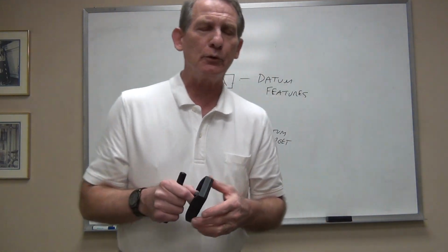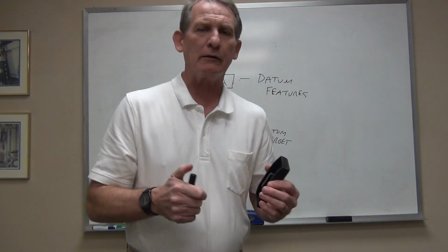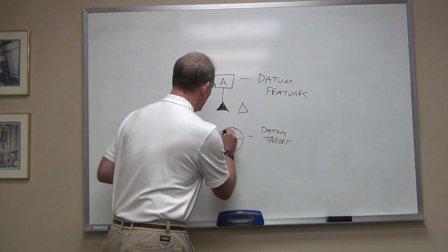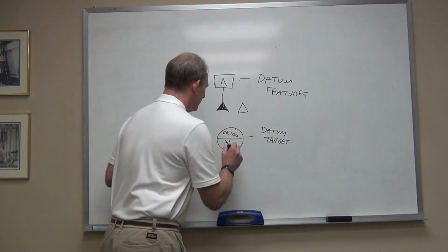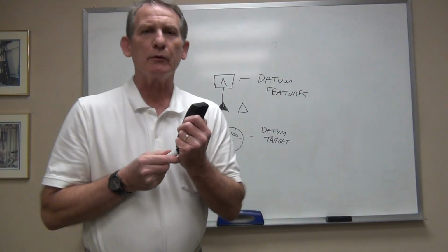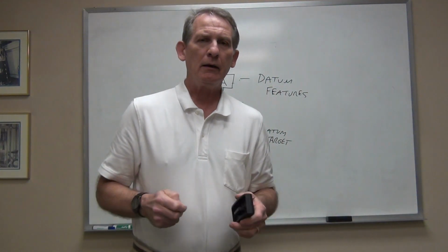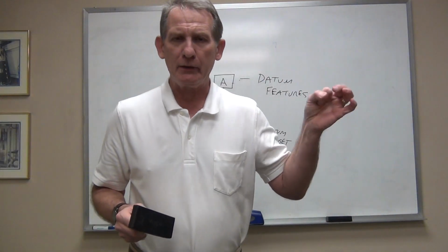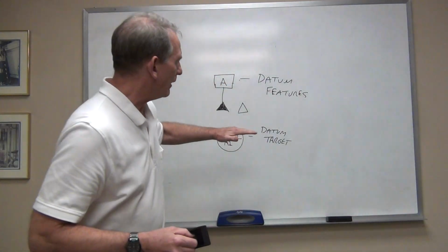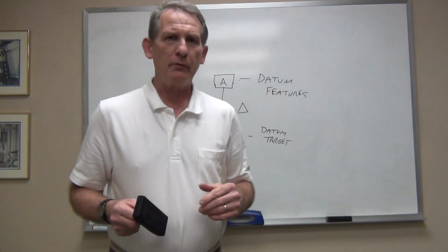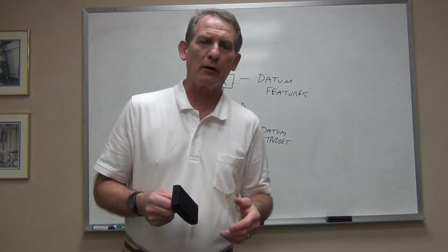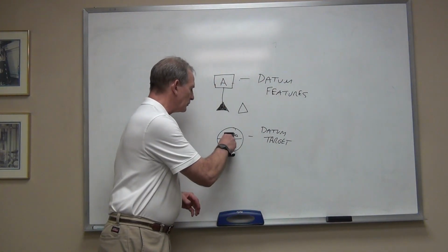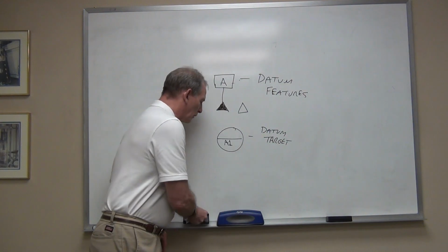But in the design of the fixture, I may have to identify that I want a 1-inch diameter spherical radius tooling ball or something like that, or I want a contact area that is a 1/2 inch in diameter. I can specify the nature of the contact point and how many there are in this upper area. Again, that's very specialized. It's more into the tool design realm.